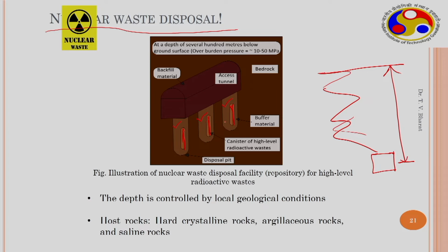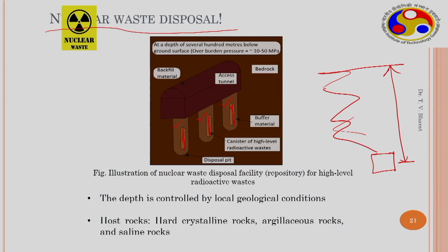In that case, the unsaturated flow through the bentonite material is important, and secondly, there may be thermal gradients across the bentonite layer. So thermal flow, thermal conduction is important, and the mechanical behavior. When the bentonite is saturated by the water coming from the saturated rock mass, bentonite applies huge pressure on the surroundings. This mechanical pressure could be as high as 40 megapascals, depending on the type of soil.